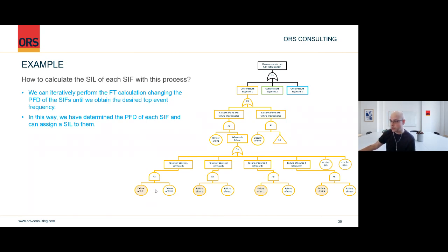That's absolutely true. Yeah, we mentioned that with fault tree analysis, it's a lot more powerful than only allowing you to calculate the frequency, because as Solak says there, you can then know what the most vulnerable part of your process is, because you can define, well, if this fails, only with the failure of this, and then that, I will get to the top event. So if you define the minimal cut sets for the fault tree, then you can get what is the easiest way to get from an initiating event to a top event.